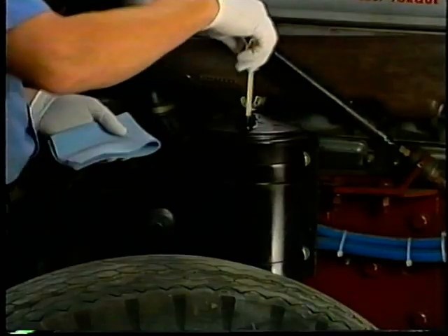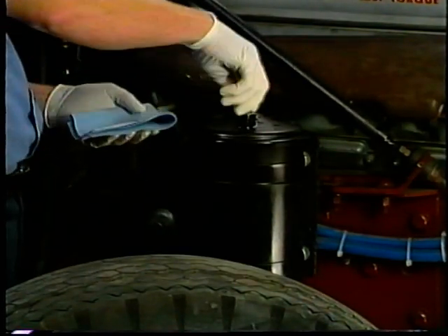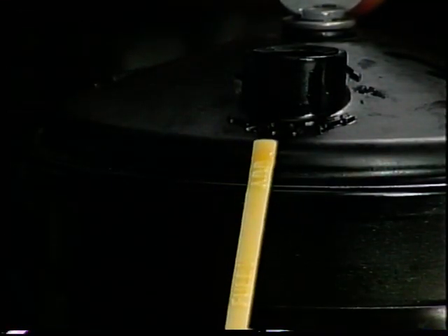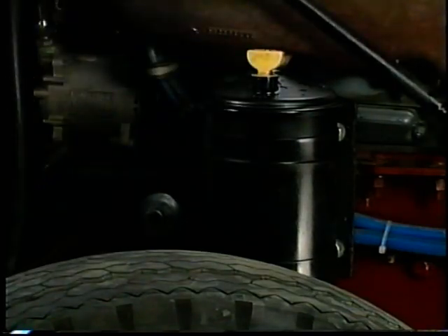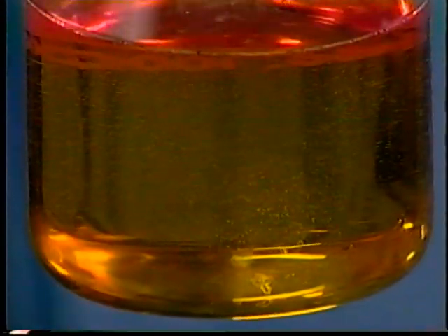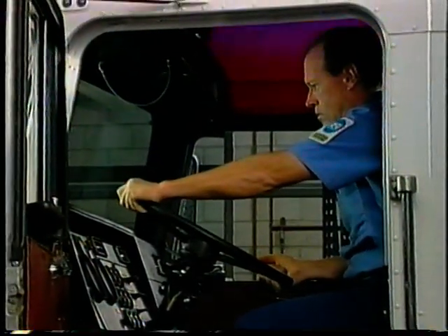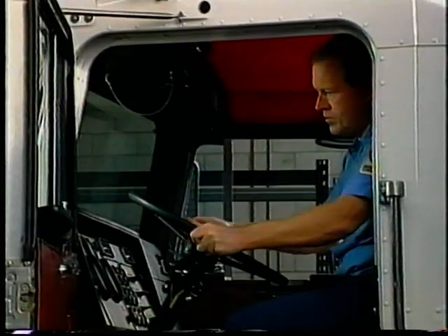If you suspect the problem is hydraulic rather than mechanical, check the power steering fluid. Low levels of fluid will cause increased steering effort and erratic steering, as well as a noise from the pump. Aerated fluid is an indication of air in the system or a low fluid level that can cause erratic steering effort. Follow the bleeding procedures to purge the air once the fluid is up to operating temperature.